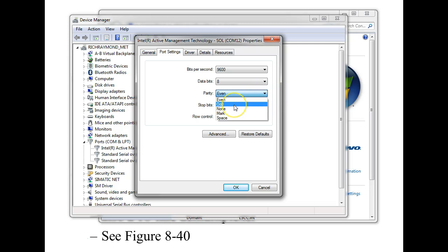So we'll leave this thing alone. And stop bits, I said it for odd parity. Or we could always make the parity a 1 for some reason. They call that a mark. Or we could always make the parity a 0, right? So we could turn it off, or not use a parity bit, or we could set it to what? Even, or we could set it to odd. And right now we don't know it because it's done for us automatically.